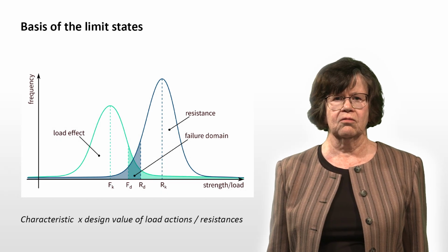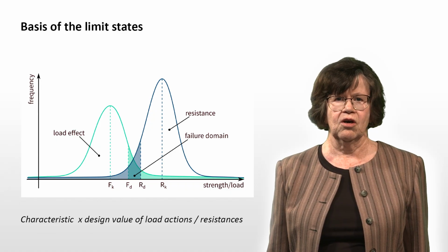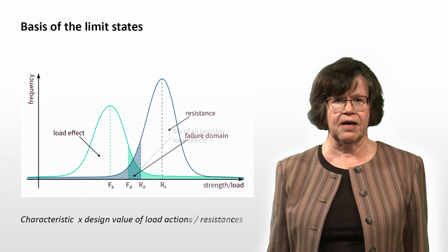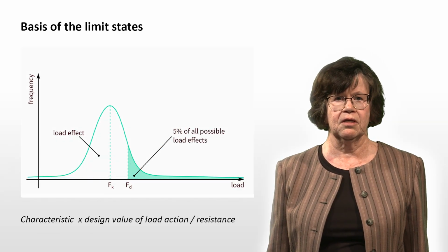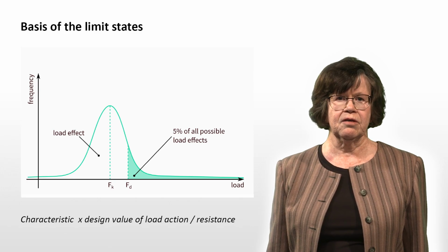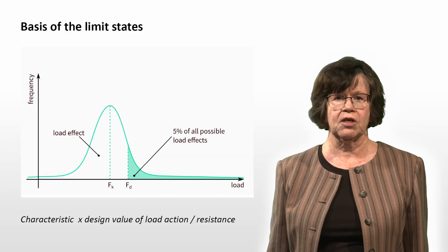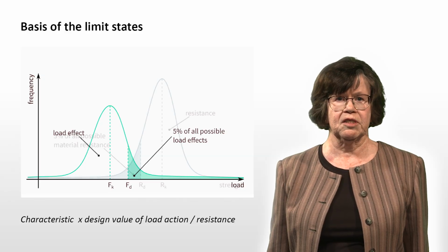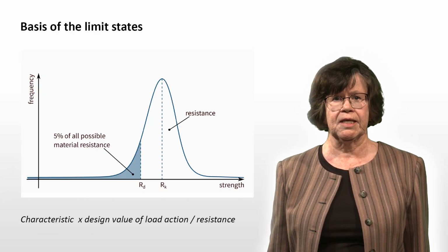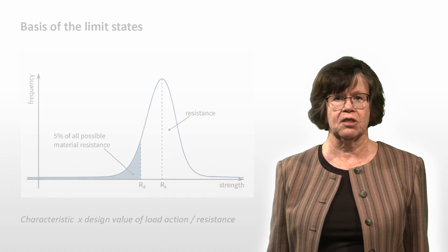Structures are designed according to limit states. The limit state describes the state of the structure beyond which the criteria of the state are no longer satisfied. A distinction is made between the ultimate limit states, where the stability, strength, brittle fracture, and other factors indicating collapse of the structure are examined, and the serviceability limit state, where deformation or vibration are checked. Exceeding the limits of the serviceability limit states does not lead to collapse, but performance of the structures is affected.